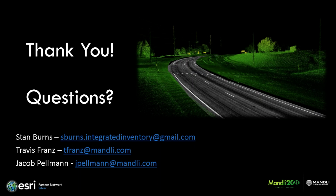It's what's called a data dictionary. You sit down with the client, and the client defines, this is what we want. We want cracking. We want lateral, longitudinal, block cracking. And then we want the severity to be noted as if it's less than 1/4 of an inch. We want that as fair cracking as opposed to poor cracking. Rutting. We want all the lanes to be driven. Or no, we just want the outside lanes. We want all the ramps to be included in your pavement distress collection. And we also want the ramps in PFES, by the way.